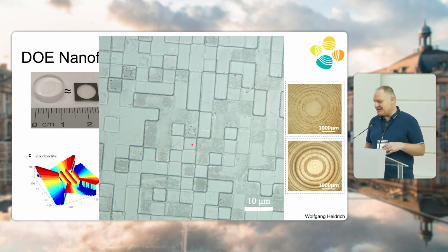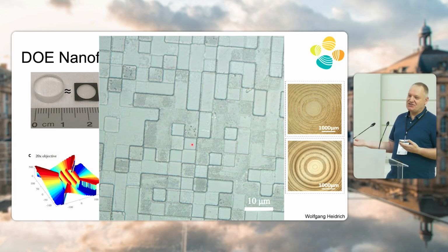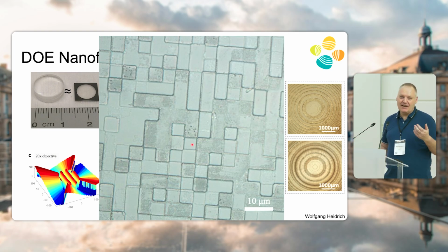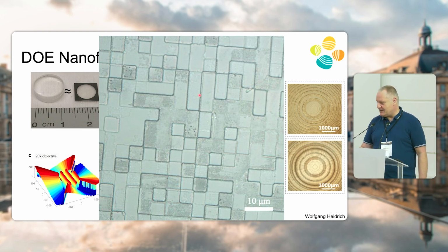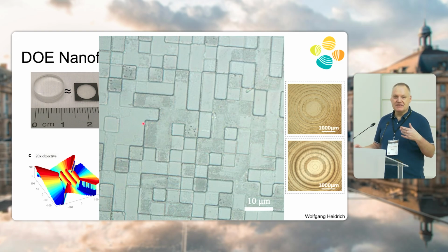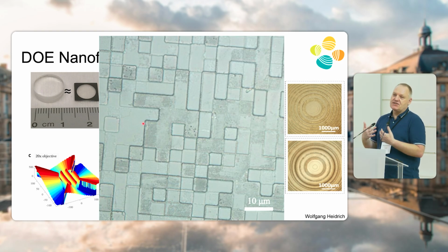The prototypes tend to kind of work, okay, but there's fabrication error. Whenever you do nanofabrication like this, there's fabrication error. Say you have a design intended to have perfect square features, and what you see is corner rounding effects and maybe some surface roughness. And it degrades the quality, right?